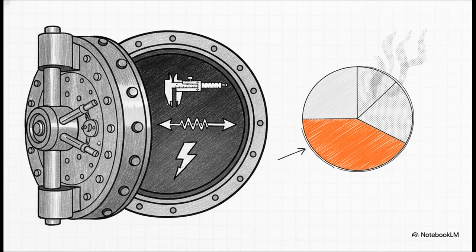The modulation index, mu, is just the amplitude of the message over the amplitude of the carrier. Bandwidth is simply 2 times your modulating frequency. Total power equals carrier power times 1 plus mu squared over 2. And efficiency? That's mu squared over 2 plus mu squared.